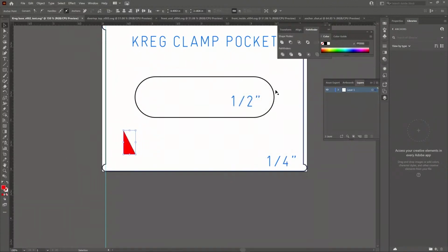Worth noting, currently the only way to create custom anchors is in the design software, not on tool. So this gives you the advantage that you can bake in these positions in advance. So now I'm just going to come down here and have it align in that bottom corner. I'm just snapping it there. That's easy to do. So now instead of measuring my position relative to that dog bone detail, which I'm not interested in, I'm interested in my straight edges.